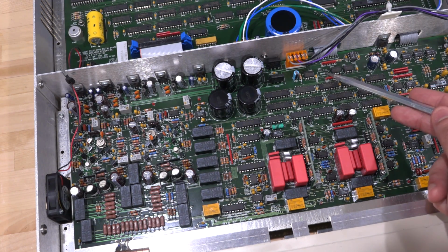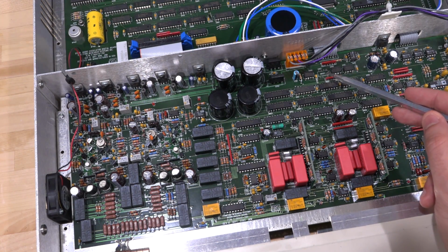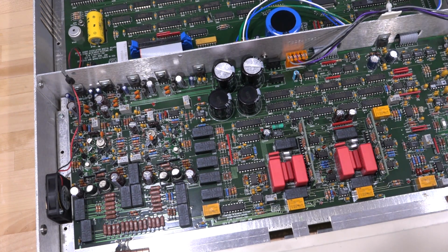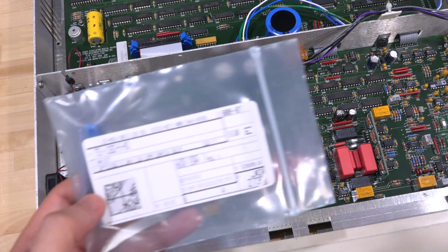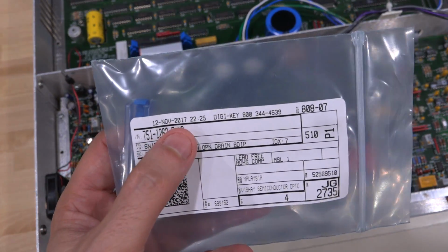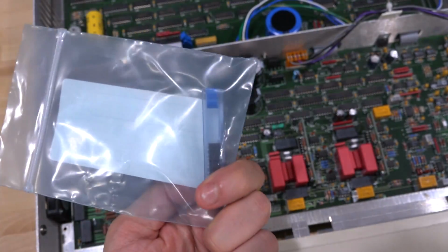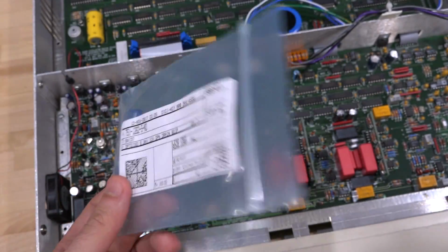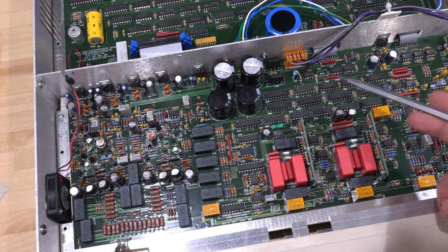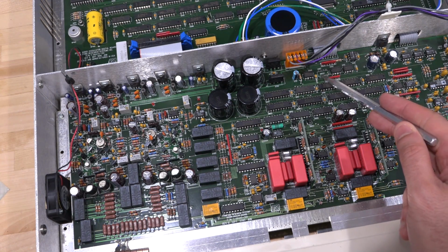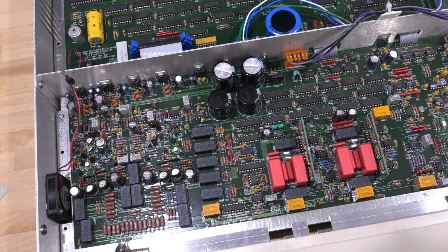So I looked this up, and I know what this is, a part number 6N137, and what do you know it? If I look through my parts, I actually found one that I had ordered from a long time ago for some other application, I think. Look at the date of this, it's 2017. One of the benefits of never ever throwing anything away. So I have a few of these so we can quickly replace it and see what happens. I'll put a socket here because it's really annoying to take off otherwise.